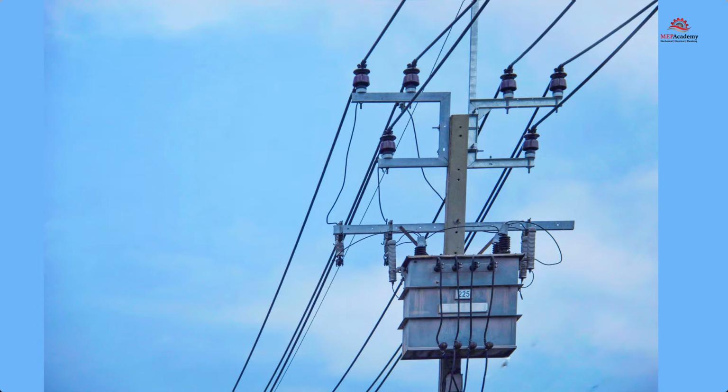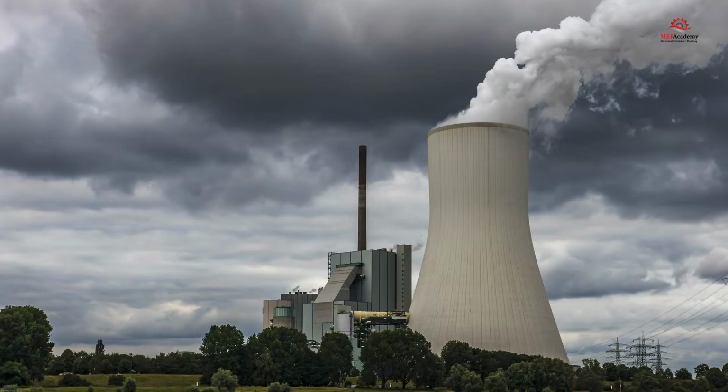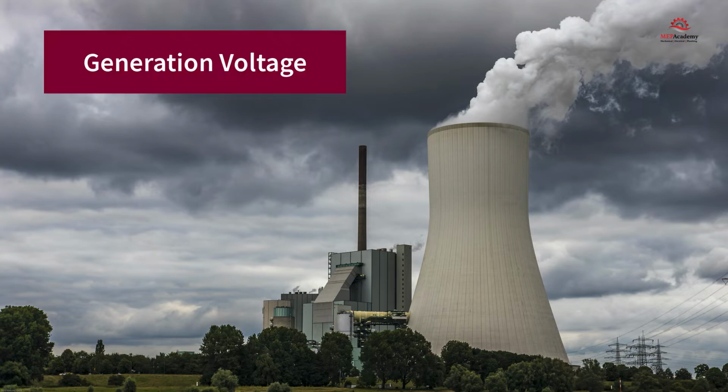Three-phase transformers. Using a three-phase transformer is like a single-phase transformer, except that we have 3 single-phase windings instead of 1. With these 3 windings, we connect them together in a Y or delta configuration or a combination of the two. Three-phase power is the most common way that power is produced. Large-scale power plants generate voltages of 13 kV or higher.